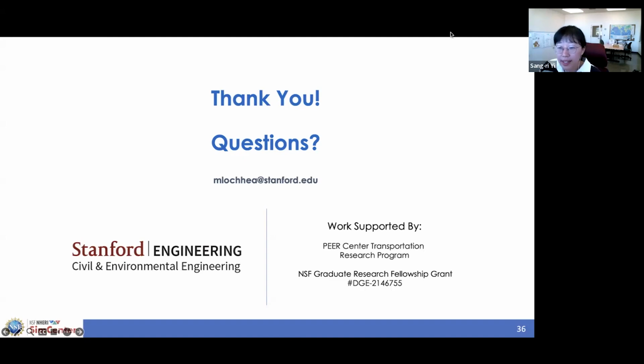The first question is: is regional simulation computationally feasible if you use the PLoM model? How much faster than OpenSees analysis is this model? Thank you so much for that question. The short answer is yes. Once we have a trained PLoM model, we can have a computationally feasible regional analysis. Once the model is trained, the computation time for a PLoM model is about 0.4% of OpenSees analysis. So it is a lot faster.